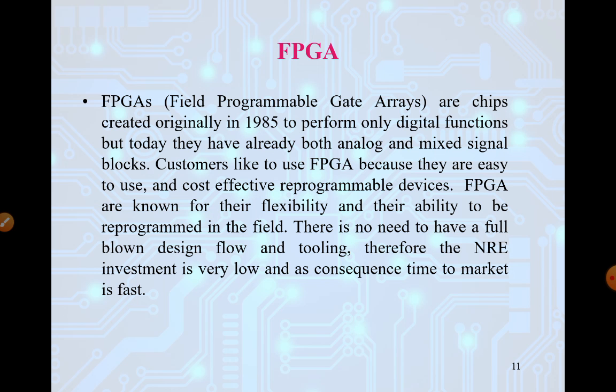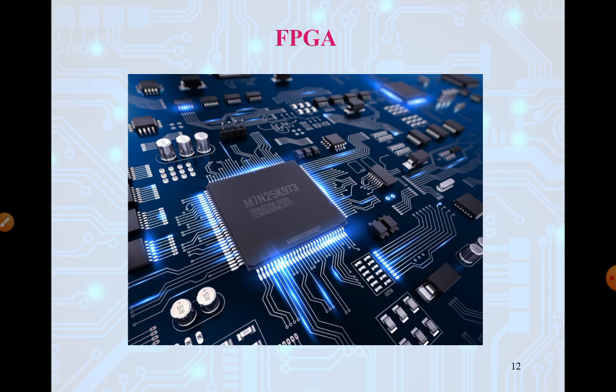By changing the program we are changing the hardware within the FPGA. Within an FPGA there is a sea of gates, arranged as LUTs. Basically they are multiplexers designed to perform as any gate or any function, by changing the inputs and select lines. So the initial investment is very low because we can reprogram and test it with a single piece maybe lakhs or 10,000 times, and the time to market is also very fast. So this is the image of FPGA.